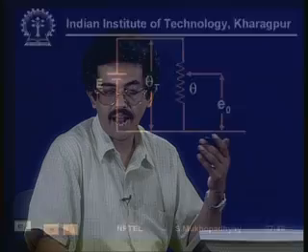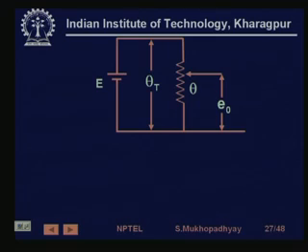For example, typically, a potentiometer. I was talking about a resistance, right. So a potentiometer is nothing but a resistance. So for a potentiometer, the position signals, potentiometers typically measure position, so the potentiometer will be connected to this variable point. So as the variable point moves, the voltage that you will get will be directly proportional to the position, right. So in this case it will be instant to instant, and since the position is actually a mechanical variable, there is not going to be too fast a movement.